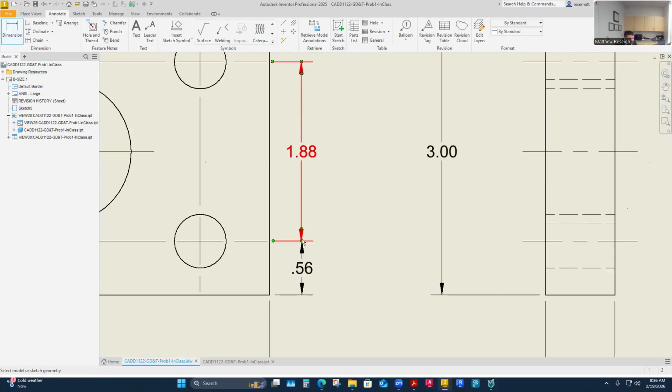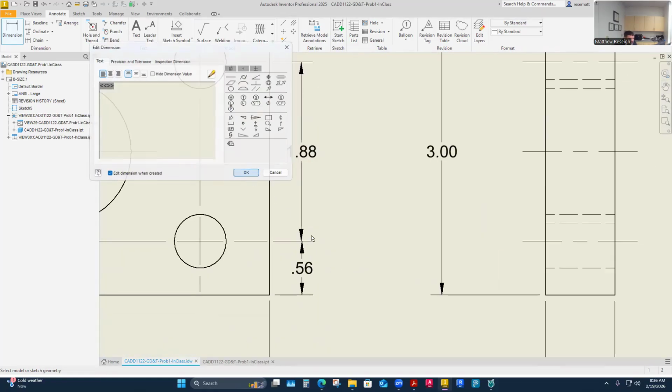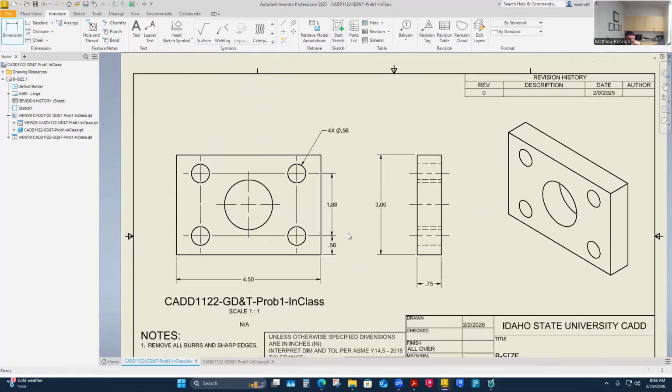And we'll talk about why GD&T will allow you to do either baseline or chain dimensioning. It's because of the theoretical exact. When we establish basic dimensions, we're saying there is no problem with that dimension at all. Working from that dimension is no problem because it's a theoretically exact dimension. And so you can chain dimension, which is seemingly weird because it seems like the most inaccurate kind of dimensioning, only it's not in GD&T when the chains are basic dimensions. They're actually theoretically exact, so there would be no error in them if you could actually make it that accurate.